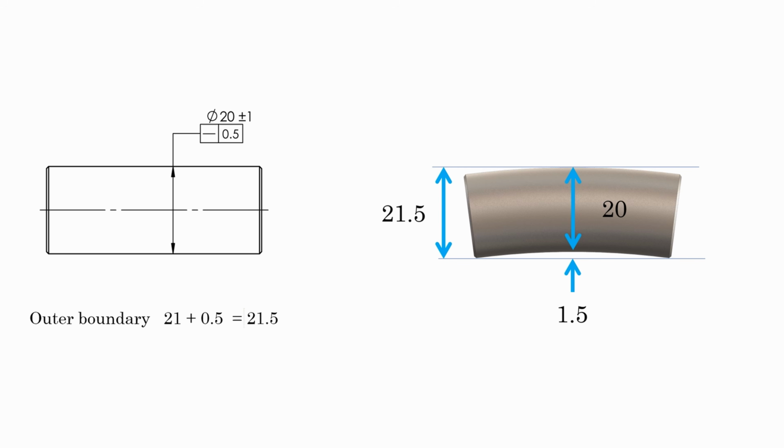It doesn't cross the outer boundary, but the pin is rejected. The straightness tolerance is out of the limit of 0 to 0.5 mm. So we cannot trust the outer or inner boundary as an acceptance boundary for inspection.